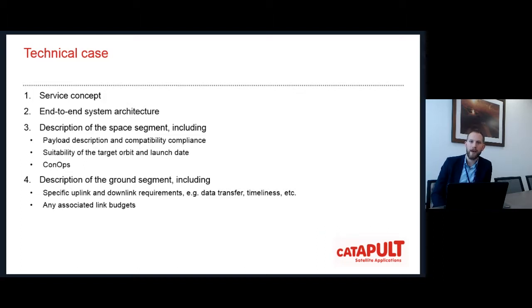And finally, also a ConOps, a concept of operations: how the spacecraft is going to be used on a day-to-day basis to provide this service. Who needs to provide tasking? How is that going to be uploaded to the spacecraft? How often is that going to be uploaded? Does the spacecraft need any ground interaction at all? How the payload will be operated, duty cycling, and so on and so forth.